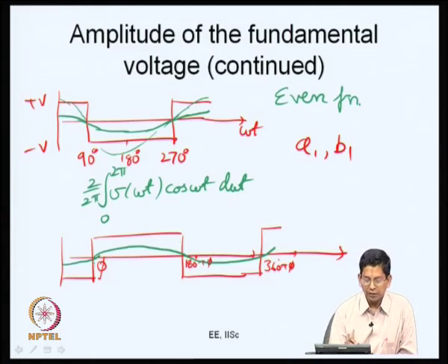So, what is being done if the phase is known? What we are trying to do is multiply by a sine wave. What is the frequency of the sine wave? It is the fundamental frequency, that is the same periodicity as the parent waveform in question, right. Now, what should be the amplitude of the sine? It is unit amplitude.